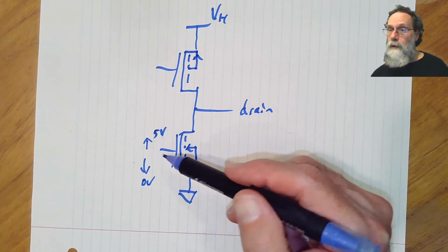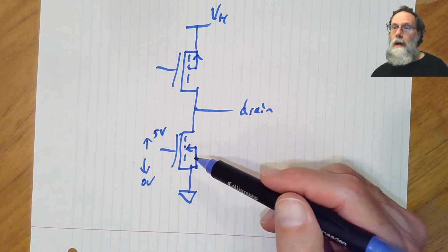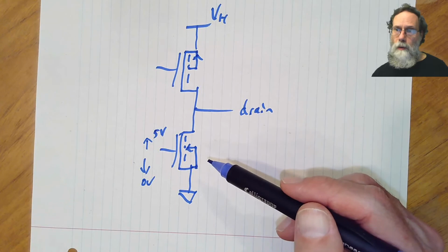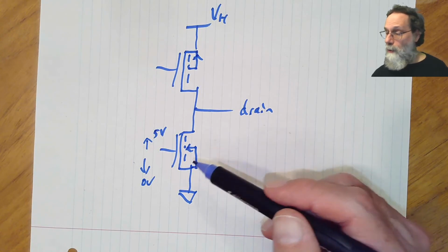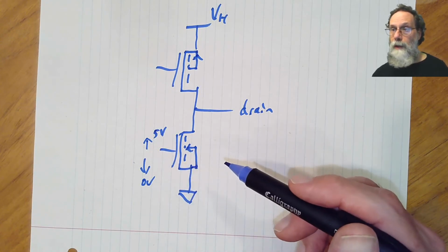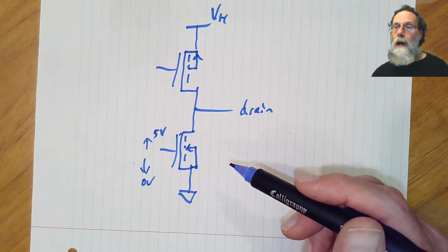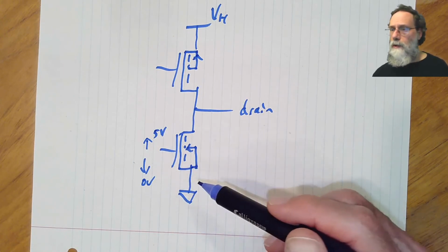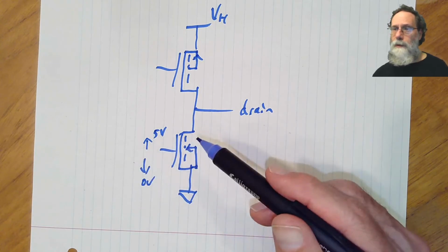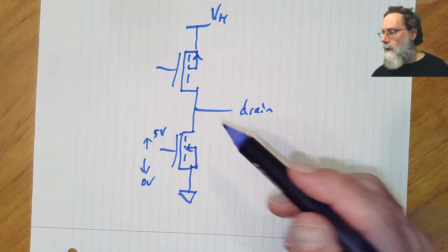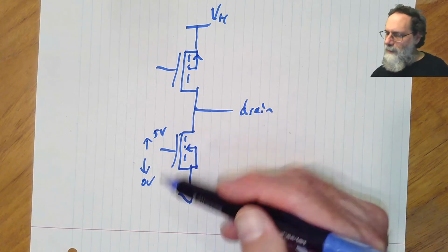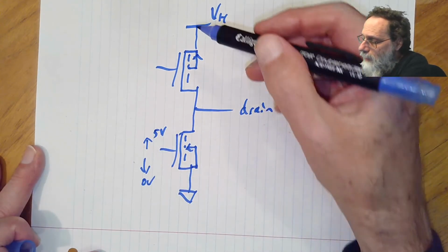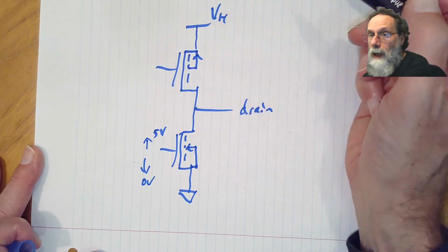The threshold voltages for these transistors is one of the specs you get on the data sheet, and they can vary quite a bit. The ones that we were using in our labs were low threshold ones, so that we could operate this thing at 3.3 volts. But you can get power transistors that have like 5 or 6 volts before they start even to turn on. So let's look at typical logic levels, 0 and 5 volts. What does it take to turn this one on and off?